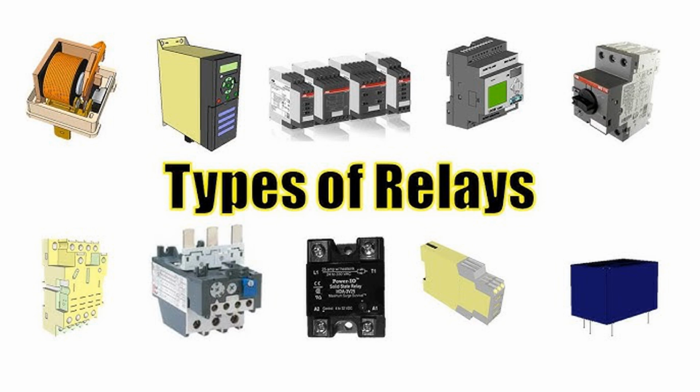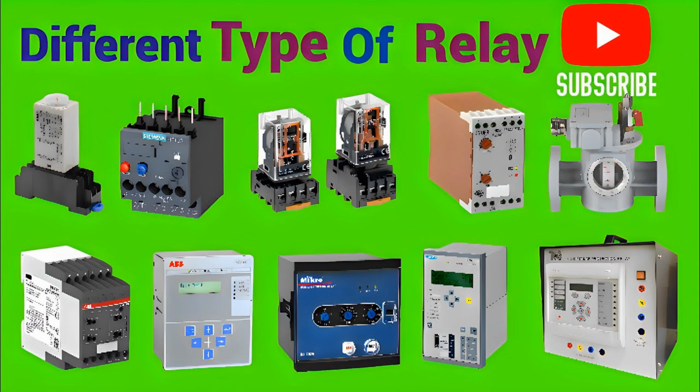When one coil is energized, the relay changes to a particular state, either set or reset. Magnetic or mechanical latching mechanism. This mechanism keeps the relay contacts in their current position after the coil is de-energized. This may involve a magnetic field or a mechanical latch that holds the contacts in place. Contacts. The relay typically has normally open (NO) and normally closed (NC) contacts, which are held in position by the latching mechanism.